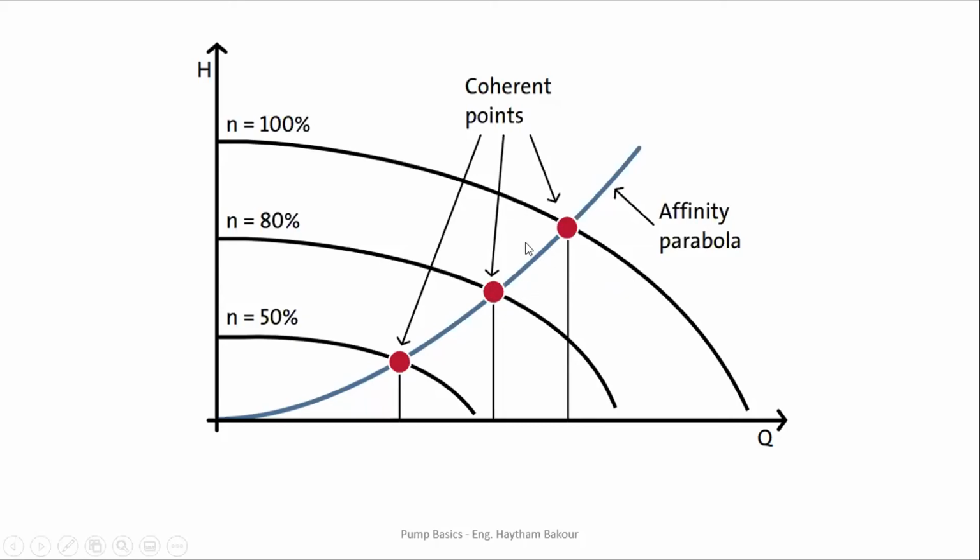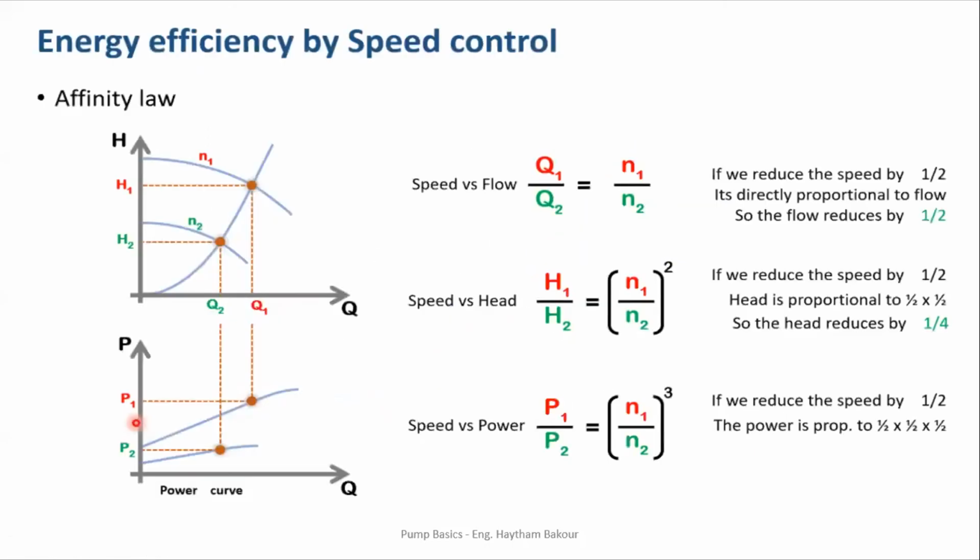At peak hours, at 100% rotational speed, it is at the maximum flow rate, while when the demand drops, the rotational speed will drop too. Then we can use a smaller tank rather than the traditional bigger tanks, and the pump would work only when it is useful, when there is smaller usage of the water.